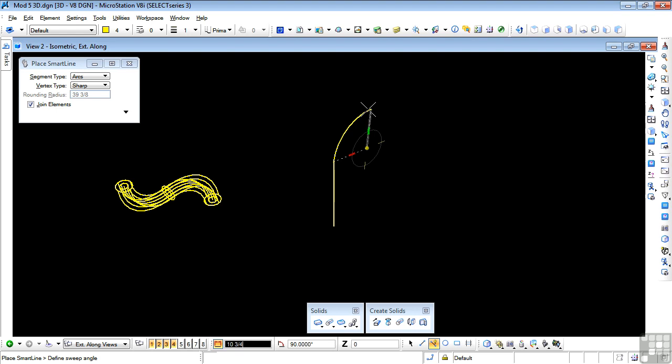Drop it to 90 degrees, press tilde to get me back into lines, drag a line, sharp corner, change the compass, come back on the axis, change the axis, drop down a little bit. And the axis is off a little bit, so let's do a T for top to rotate that correctly, and now we can get a vertical. There we go. So there's a path in 3 dimensions.